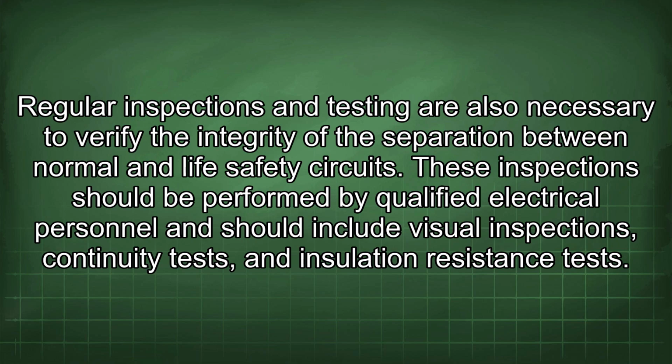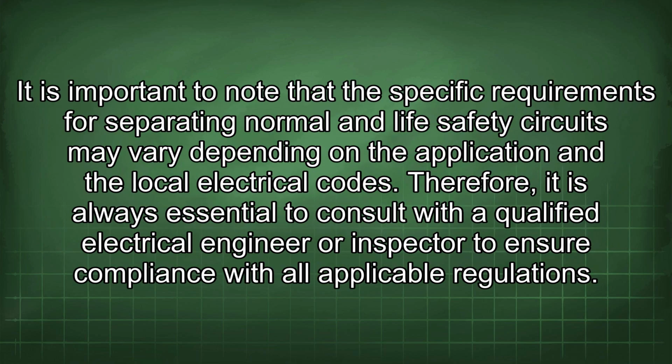Regular inspections and testing are also necessary to verify the integrity of the separation between normal and life safety circuits. These inspections should be performed by qualified electrical personnel and should include visual inspections, continuity tests, and insulation resistance tests. It is important to note that the specific requirements for separating normal and life safety circuits may vary depending on the application and the local electrical codes.